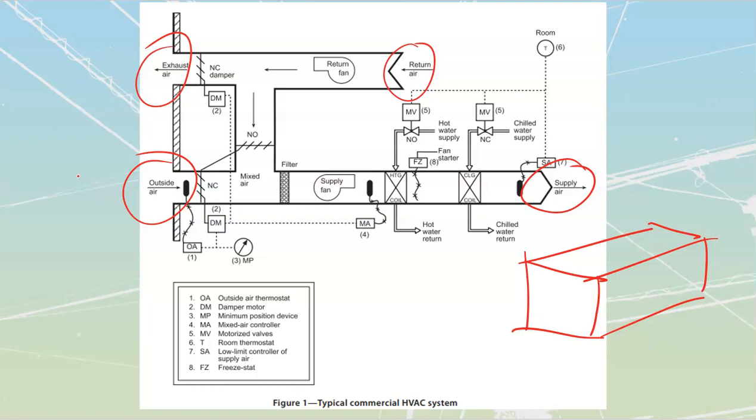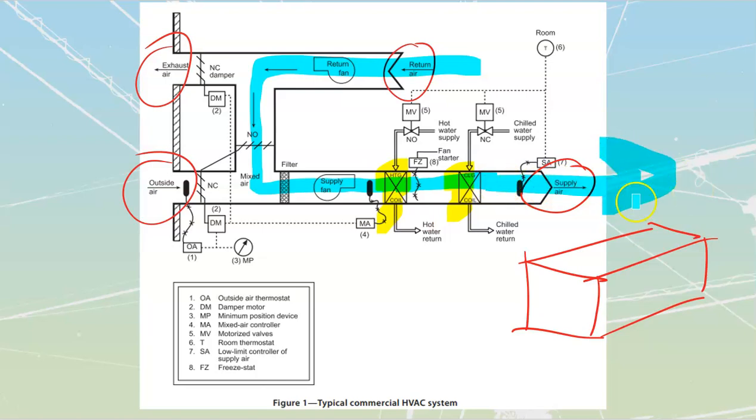What we will see inside of here is that the bulk of our air is going to follow the path from inside of the building. We are going to accelerate it through here and then drive it, filter it, heat it up, or cool it down as it passes through these 2 components over here, which are going to be radiators. We'll go a bit more in depth in that in a little bit. But then we pass that back into the building itself. And then it goes through our working and living spaces, etc., and then cycles back up and through like that. That's the way that things normally happen inside of a built-in type of system.